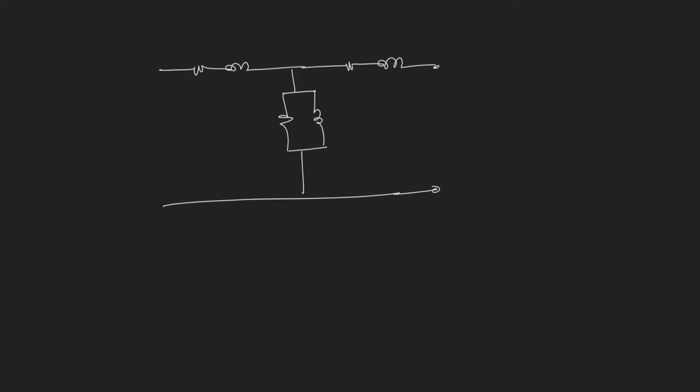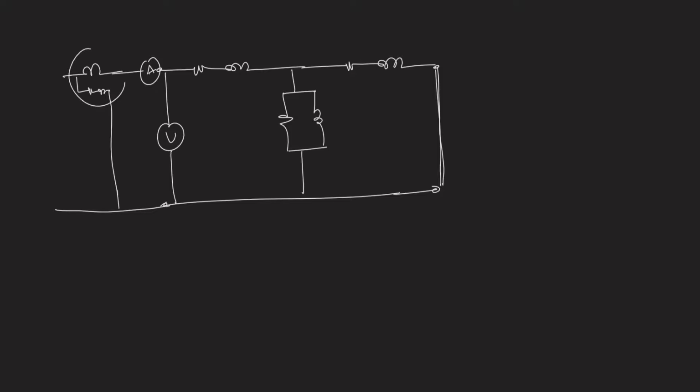Now in the case of the short circuit test, this is shorted, and similarly we keep an ammeter, one voltmeter and one wattmeter. Okay, so this is a variac.